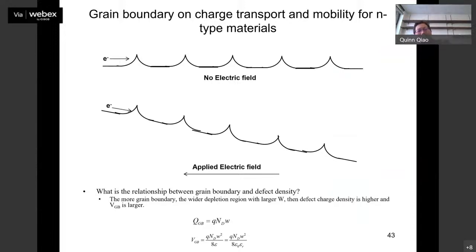Like when we are dealing with the PN junction, the bottom material is microcrystalline and some grain boundary is there. If that grain boundary lies in the depletion region, then in that region the electric field is very high. So what is the impact of that high electric field on this band bending? Oh, okay.